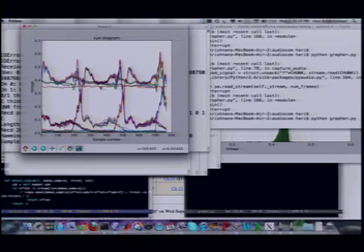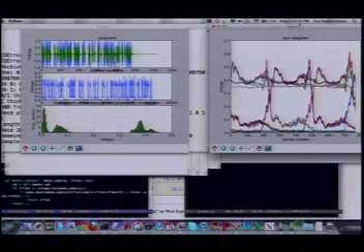But the point is that when you see the separation and you see a point in the middle with a big gap on this eye diagram graph, and then you see a separation between these were the zeros and those were the ones, which means you could threshold somewhere in the middle and separate out which bits were zeros and which bits were ones, it means you're cooking. Things are great. You can see there's some distribution of what the ones look like in the empirical data, and a distribution of what the zeros look like. This is not going to be a Gaussian at all. I'll explain why that is in a moment.